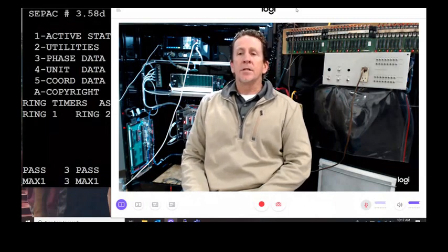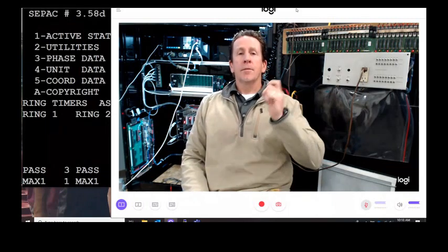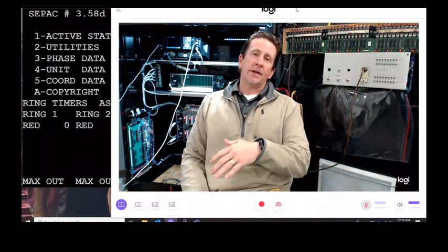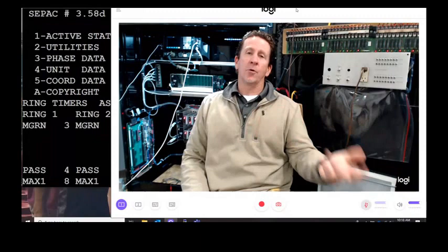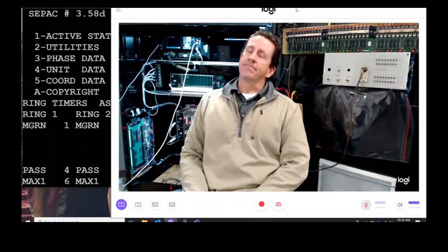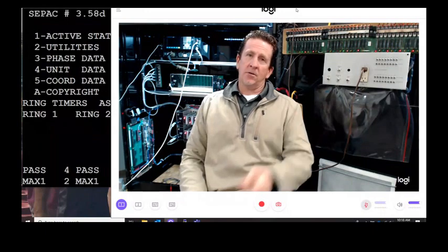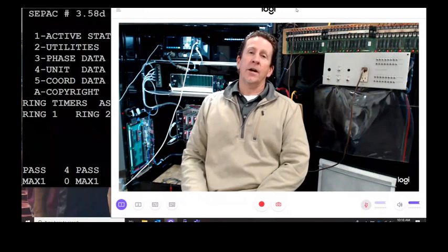But what happens is you get a bad load switch, you swap it out. Ironically, people put that load switch back in the cabinet. They don't know enough to throw that bad load switch away. If you're one of those guys that want to collect load switches and take the cubes out and try to get one good one out of three, God bless you.